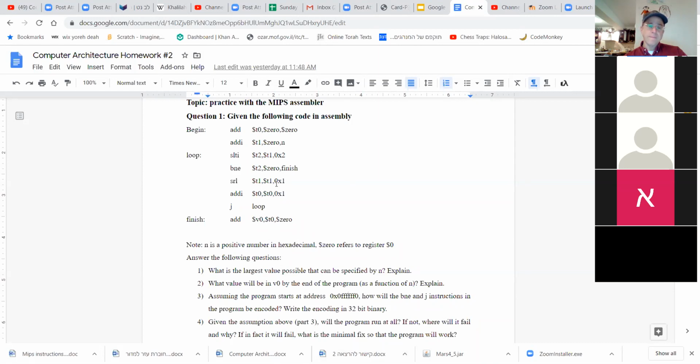Doesn't the branch also have that problem where it will also copy the beginning of the bits? It's not just the jump, is it? I think the branch is fine. It's just a jump. The branch has no problem like that. The branch takes the whole PC as it is and adds an offset. It just takes this whole FFF, whatever it is, or it'll be 1 and then 0, 0, 0, something, and then it'll just subtract from that what it needs to, and that 1 will drop away, go back to a 0 again, as it does the subtraction.